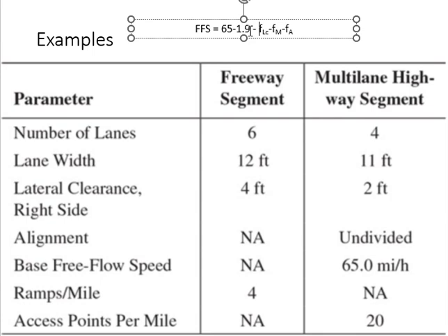If it is not undivided, we will add the exact value for the left hand side. If it is a divided highway, I need the exact value for the left hand side as well, and I will add that value itself. It will not be plus 6. It could be 8, it could be 9, it could be 0, whatever it is. Plus 6 is only fixed for undivided highways. So it will be 2 plus 6 here. But if it is divided, then you should ask for the lateral clearance on both sides, separately, so you can add it. Clear or not?